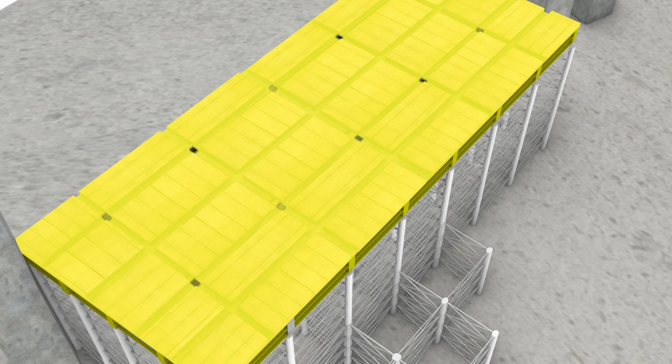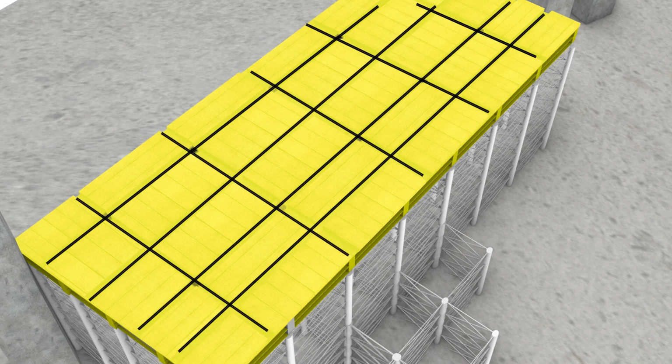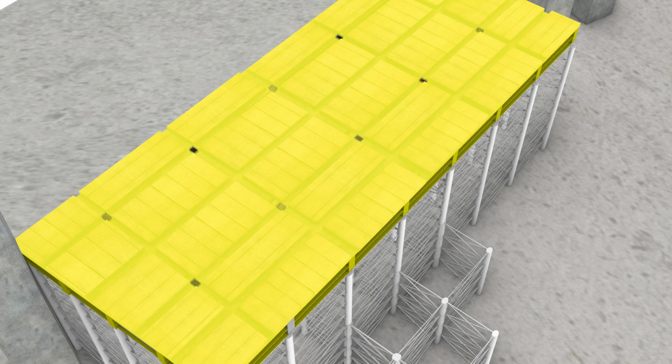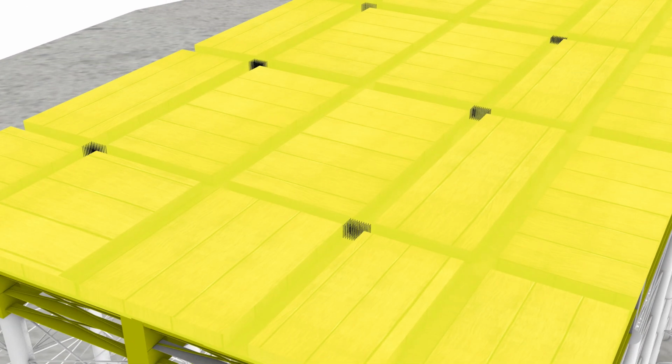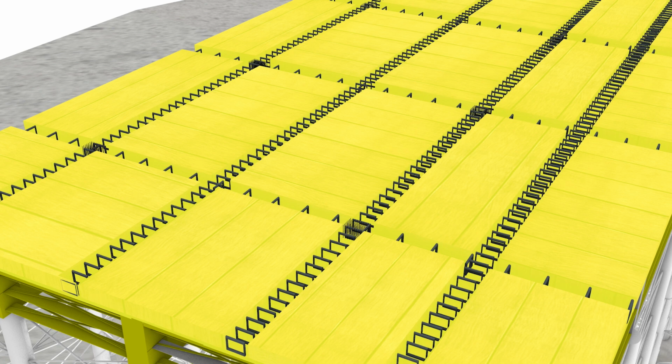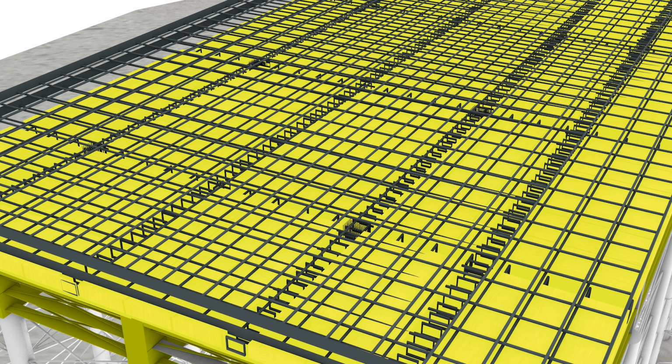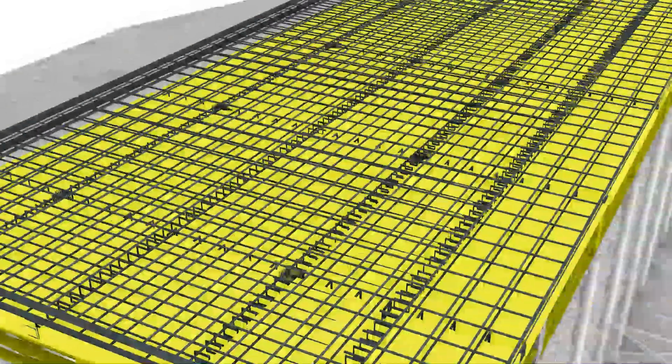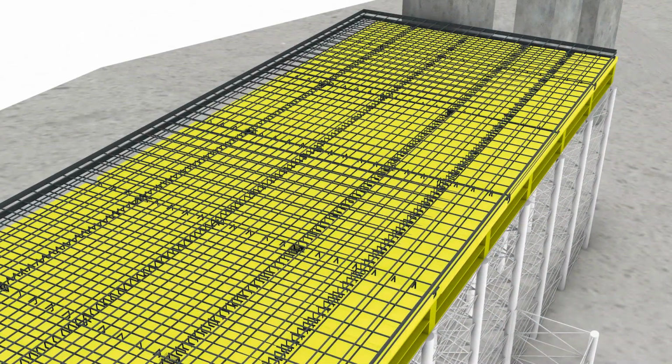In large slab areas, beams are necessary to resist bending. By forming recessed channels in the formwork, concrete fills the deeper section, allowing beams to be monolithically cast with the slab. In the beam areas, additional reinforcement is placed to resist bending moments. For the entire slab, double reinforcement is used, placing bars at both the top and the bottom. Bottom bars resist tensile forces, while top bars handle compressive and flexural stresses, preventing cracking and deflection.